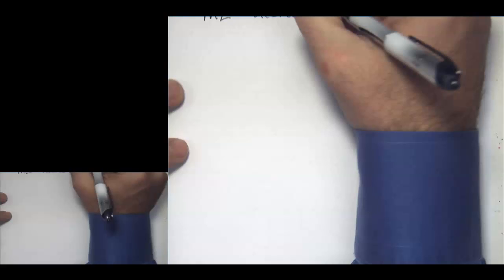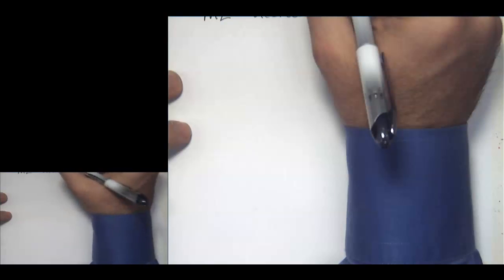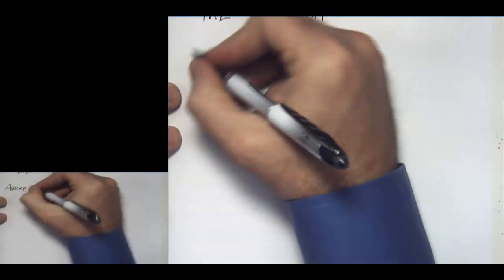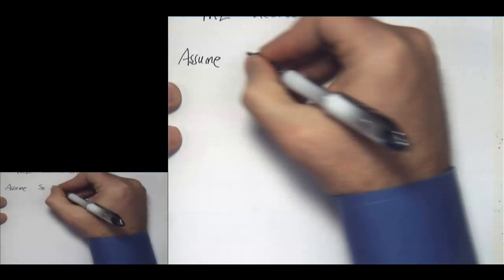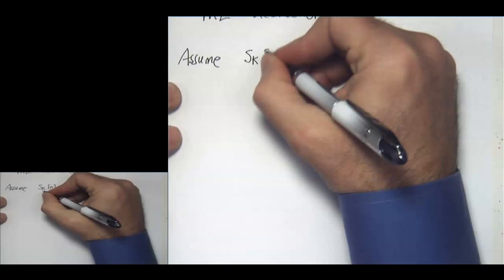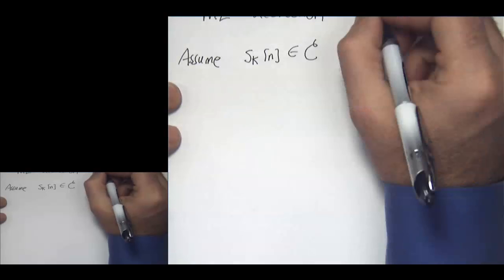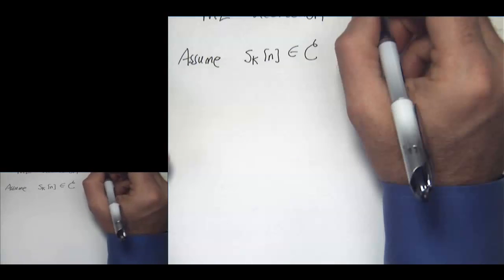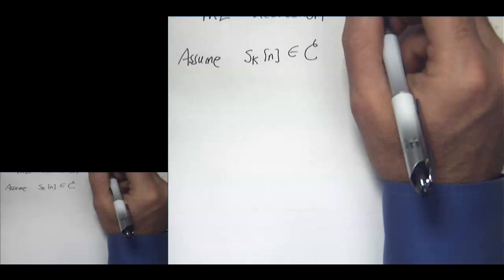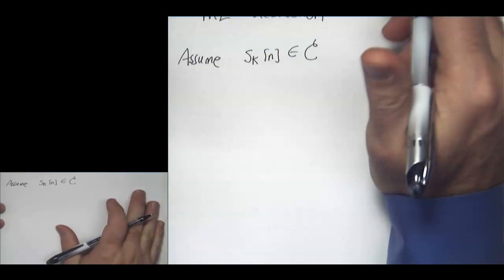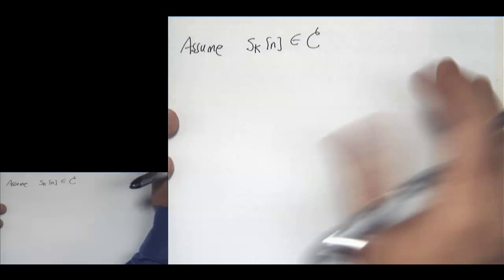So first of all here, we have to talk about what constellation is used to create each set of symbols. To make this problem easy, we're going to assume that every symbol sent on antenna k comes from the same constellation C. But you can actually allow generalizations where you have different symbol constellations for different antennas. Now that only makes sense when you have some feedback, and since we probably won't get to that in the course, we won't discuss that.